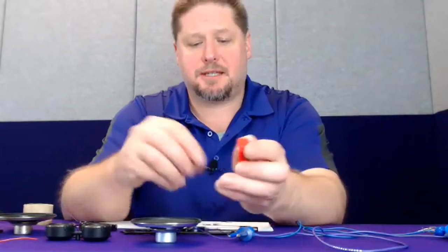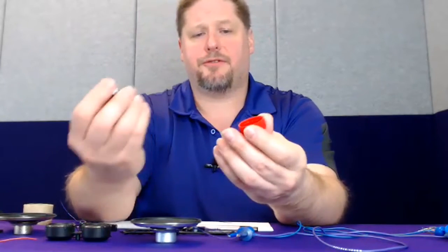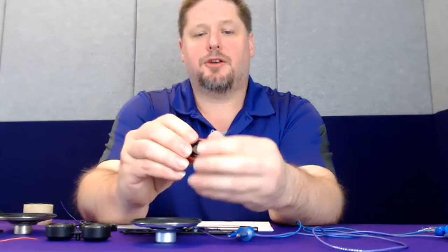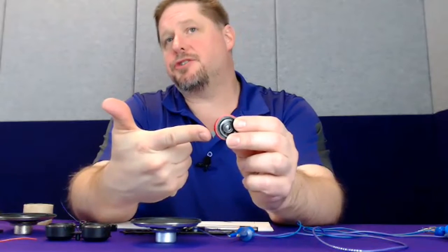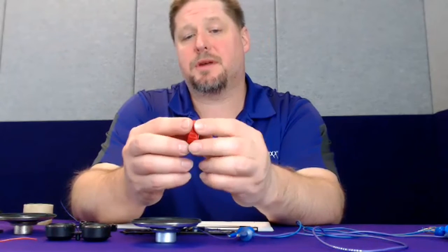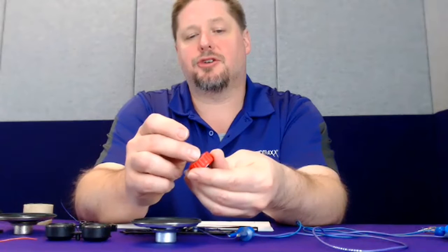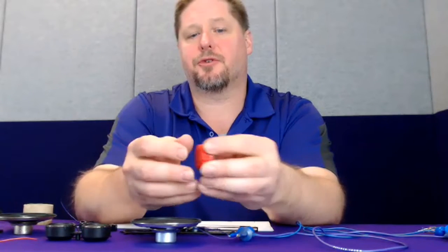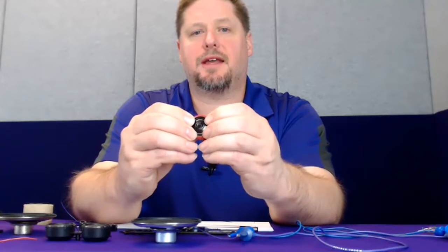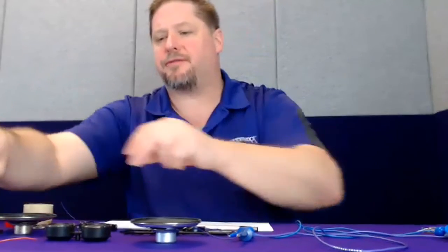But here in this case, I've got a soda cap. That's just a soda cap off of a Coca-Cola bottle that I took our 28 millimeter round speaker, and you can fit right in. The biggest thing about using this is to make sure that you wash it and get all of the soda residue out of the cap, because once that soda residue gets onto the speaker, you're going to ruin the speaker. Then you can drill a couple of small holes on the back side of it for the wires to come in. It's just a perfect fit, and you can just snap it right in or put some silicone on and hold it in place. So you can find all kinds of good baffles.